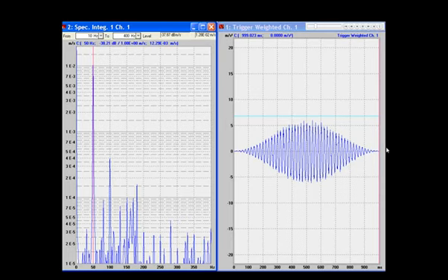When you look at a time domain trace on an FFT analyzer, you don't normally see this. It's actually done hidden in the background so that we don't worry about it. But when it comes to certain types of measurement, you need to be mindful that that is actually what is being measured and analysed on your analyzer. The beauty of getting rid of the step function at either end of your window means that we get rid of these sidebands that were false, and we get rid of the truncation error. The trade-off is you get a little bit of width to your analysis.